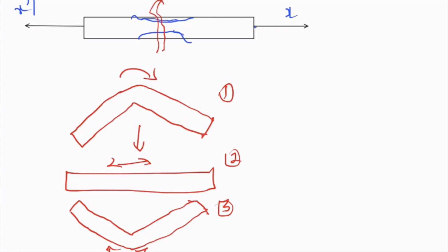Break this shaft into two pieces by means of a static load. You have to reach its yield point. Suppose the yield point of this shaft is around some 100 megapascal. You have to reach that value to make this thing yield, and you have to keep this value higher and higher, and you have to reach the ultimate situation, and then after it will break into two.